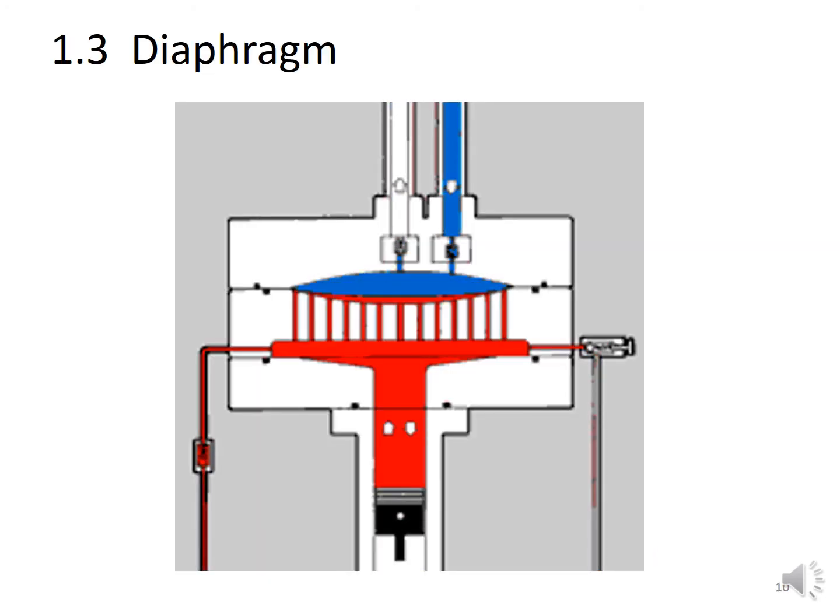Diaphragm compressor. Now what is the diaphragm compressor? As the name itself speaks, same like diaphragm pump, this one also is diaphragm compressor. What is a diaphragm? Diaphragm is nothing but a thin member. You see this member? Thin member. There is diaphragm valve also. It is a thin sheet of rubber which compresses the liquid or fluid. A diaphragm compressor is a variant of the classic reciprocating compressor with backup and piston ring and rod seals. Same piston is there, but a diaphragm is used to compress the air. The diaphragm will suck the air and it will compress the air and it will discharge.